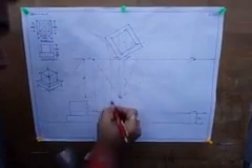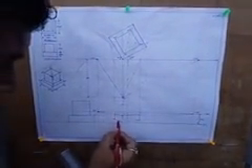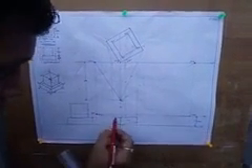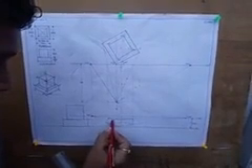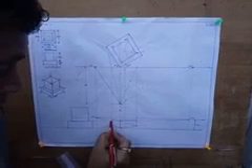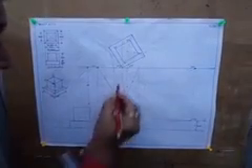From the intersection, take the line from up to the bottom, then to the points which have already vanished to the left and right. The points which are vanished to the left, mark the intersections as B dash and darken it, so you will get this face, the left face.